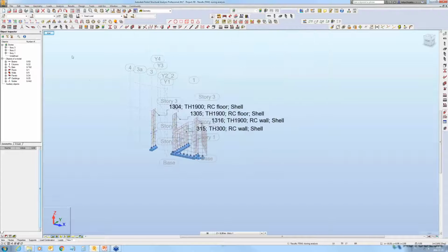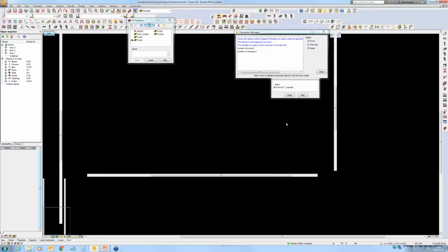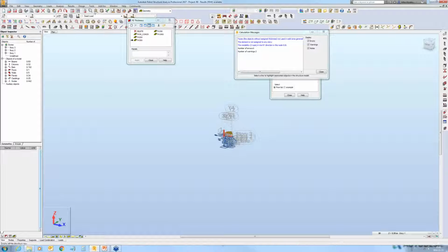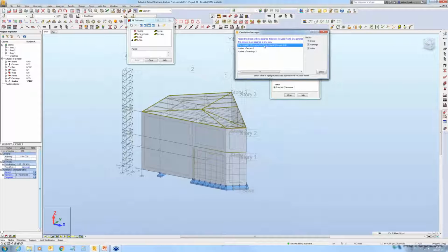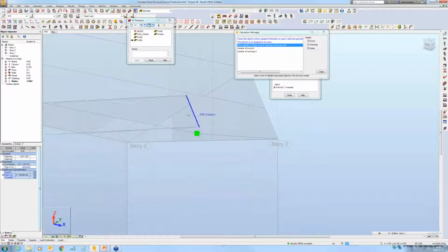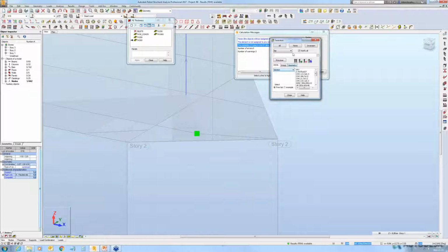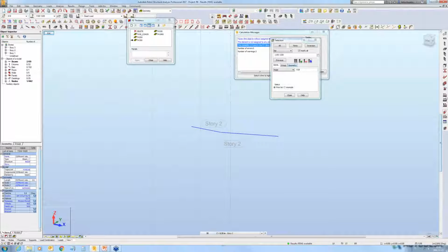Okay, so I've got another instability, but no longer any issue with those walls. If I have a look at the whole model and I select the instability, I can see that this is reported at the connection of two bar elements. So let me select those bar elements by node, and the node number is 618, so I can select that. I will open that in a new window and check if there are any releases defined for these beams.